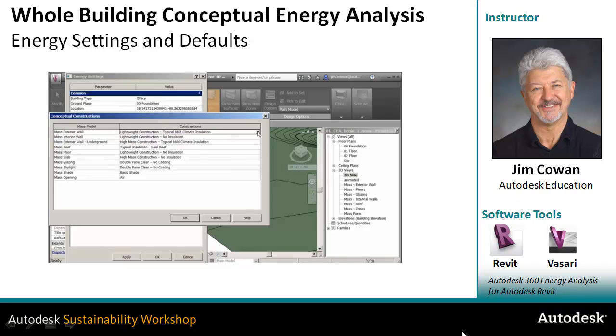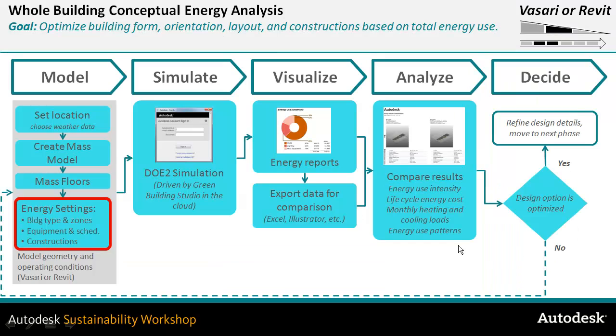So think of those as macro scale values. They're global values being applied to the different building components for the whole model. And from this, you're going to generate a surface model that can be analyzed. So those energy settings, like is it a residential, is it an office, will go about creating zones in the building where initially the whole building is maybe an office.